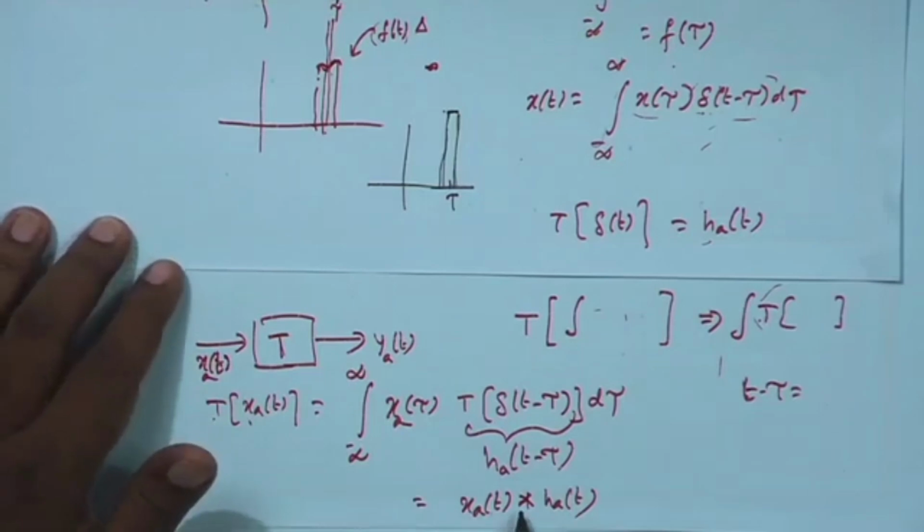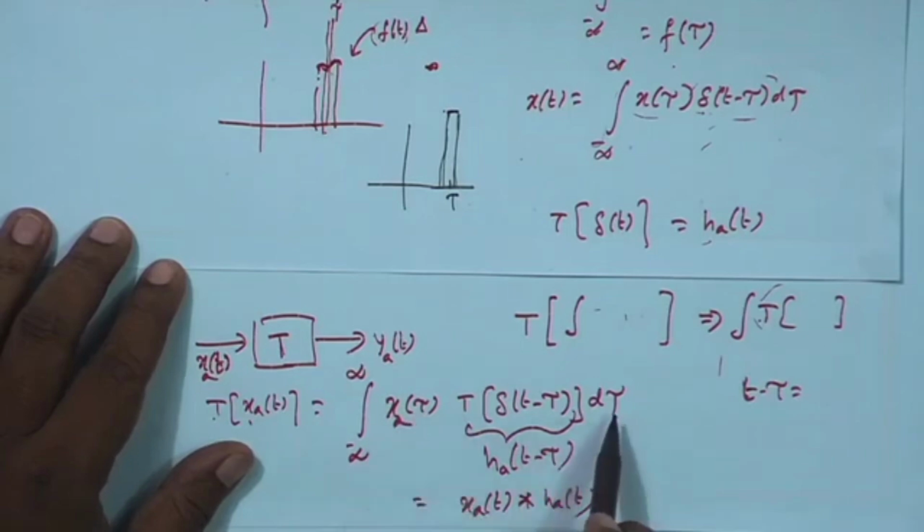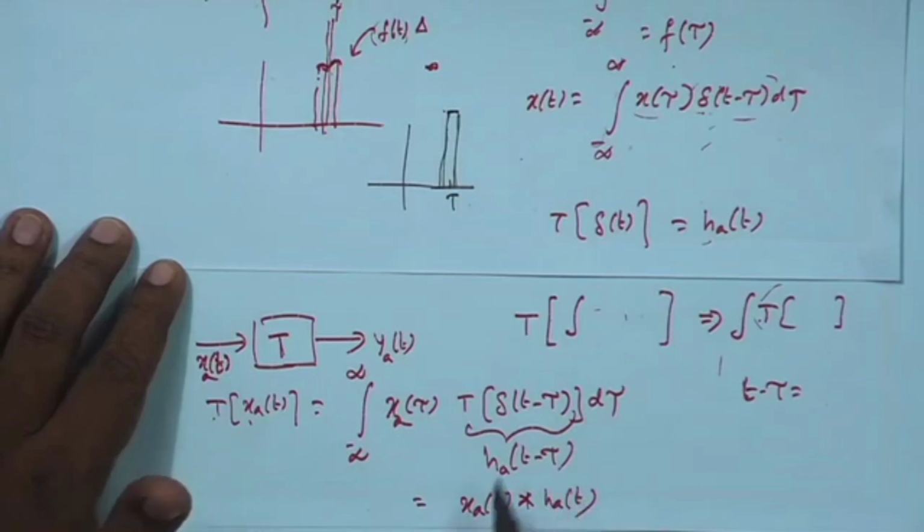Whenever you have this star, it is analog convolution, and then how to carry it out? First bring an integral, that is summation from minus infinity to infinity, write the first function as a function of some tau, local integral variable, then bring the next one h a, but instead of t, make it t minus tau, where tau was here. Okay.